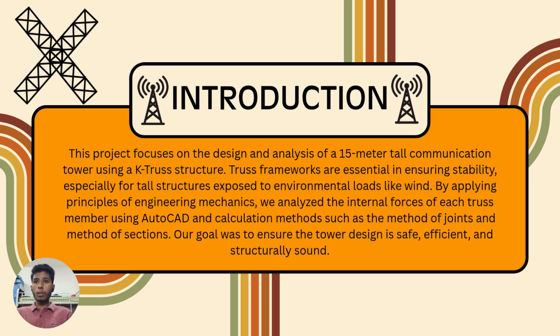For this project, we were tasked with designing a 15-meter tall tower with a 6-meter wide base. We selected the K-truss design because it offers a good balance of strength and material efficiency. Using engineering mechanics, we analyzed the tower using methods like the method of joints and sections to calculate the internal forces. We also used AutoCAD to ensure accurate dimensions and a practical design. Our main goal was to create a safe and reliable structure that could handle real world loads while staying cost effective.